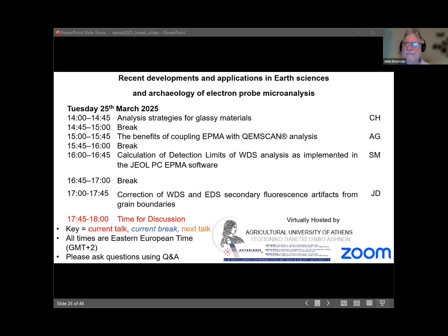It does assume a point source for fluorescence, which is not super accurate when you're really close to the boundary, but if you get more than 5-10 microns away, it's pretty accurate. So you can get all these things within a few seconds. If you're running the original PenEPMA software, yes, you have to calculate each distance from the K ratios, the intensities from each point from the boundary.